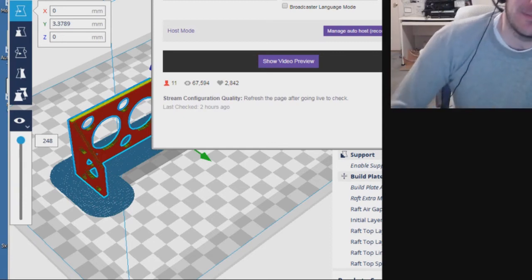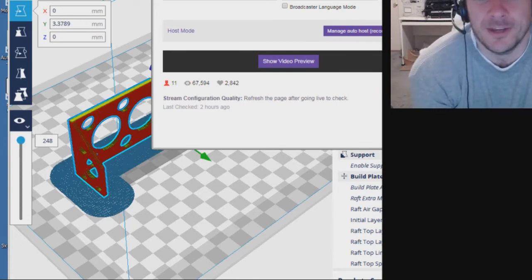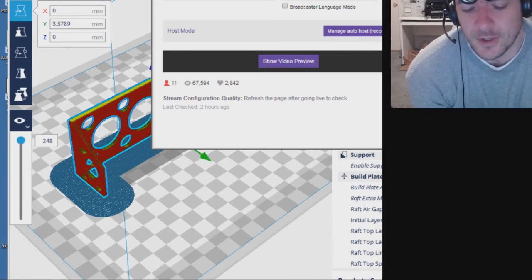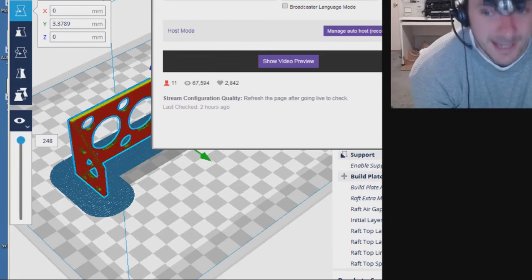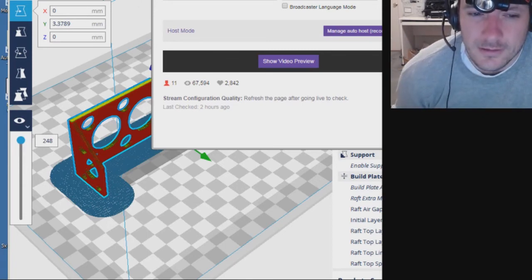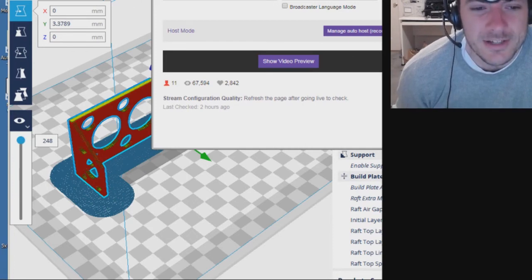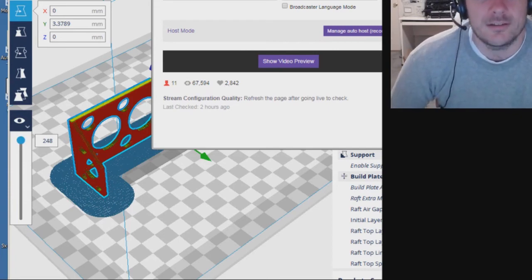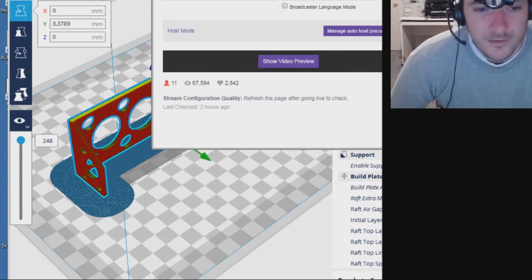So let me explain again. I believe most people that know about 3D printing know what it's for, and they own a 3D printer. It costs 150 bucks for a kit. Why not just buy one? The only people that pay a 3D printing service to do their print are people that know about 3D printing, meaning they have a 3D printer and they just didn't have time to print it, or they're running into problems. So a lot of times your prints are going to be problem prints. You have to know how to print the most difficult objects, objects that are known to cause problems. In this case, an ABS print of a long, tall sheet of wall. It's guaranteed to warp. Well, put a bunch of holes in it, it's not going to warp.